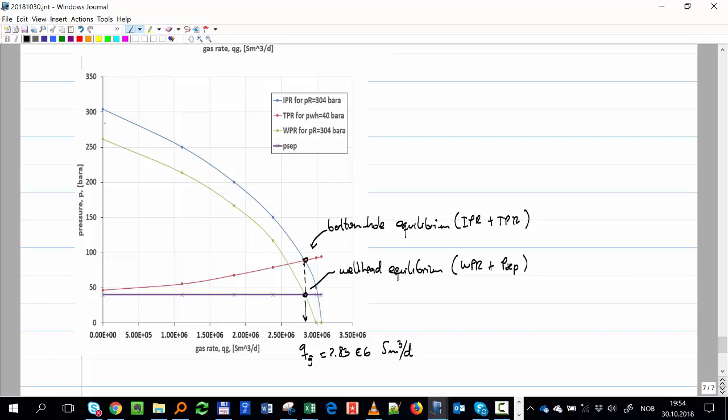That's one option, right? We said reduce the diameter. So what effect does it have on this curve to reduce the diameter of the tube? Remember, we said the delta P in the tubing is this difference, right? So by reducing the diameter, we actually create a curve which is like that. Okay? So that's one solution, but we have to reduce it pretty much to get exactly to 1.5. What is another solution?